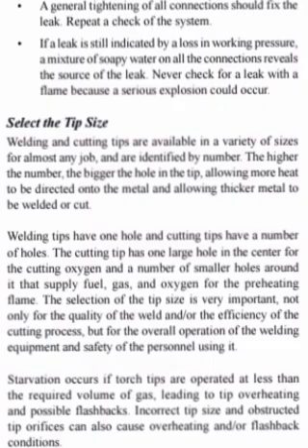Select the tip size. Welding and cutting tips are available in a variety of sizes for almost any job and are identified by number. The higher the number, the bigger the hole in the tip, allowing more heat to be directed onto the metal and allowing thicker metal to be welded or cut. Welding tips have one hole and cutting tips have a number of holes.